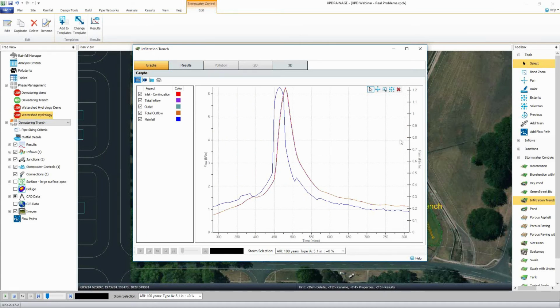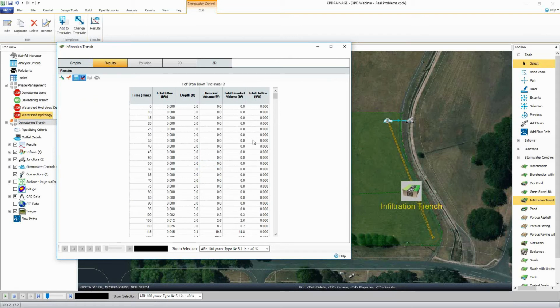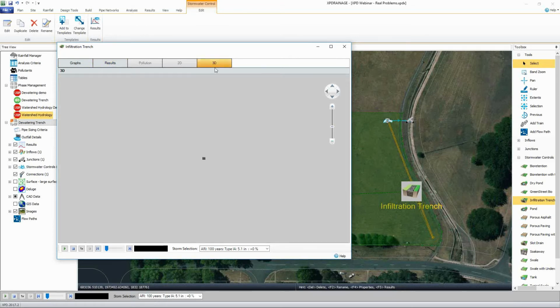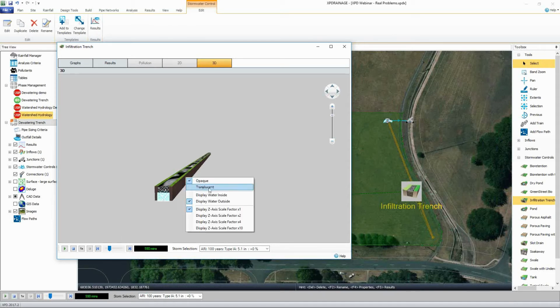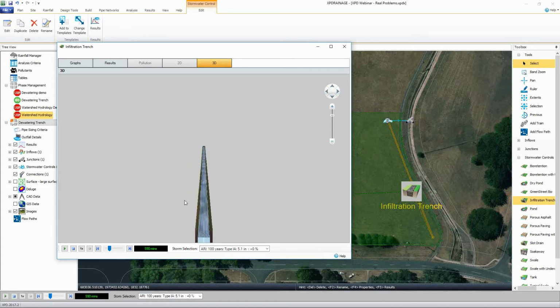We're really just getting water out, right? That's the point of these systems. Move water off the site as quick as possible. So here's the rainfall event in blue, and a little bit of a delay is water leaving this facility. We could get into all sorts of individual results series. One thing that's interesting to see, for such a long facility, it might look a bit abstract, but here is our long, skinny facility, and you see how this thing fills up over time.